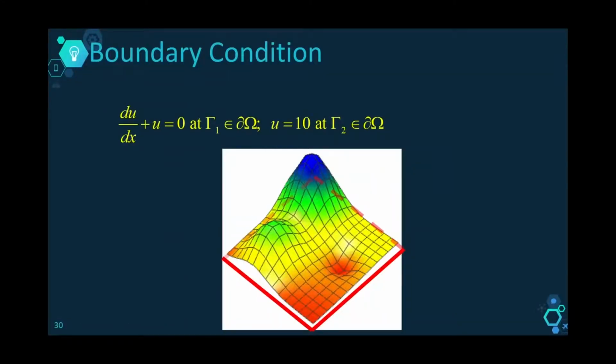And the third important element in the implementation of multiphysics is boundary condition. Solving a multiphysics problem is just like finding a solution, a distribution of state variable, which is defined on a domain. In this case, the domain represents the object or the system we want to analyze. So it's an object, that means it has a finite size, so it has a boundary.